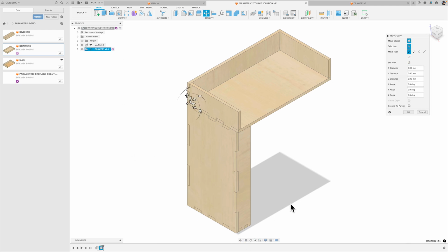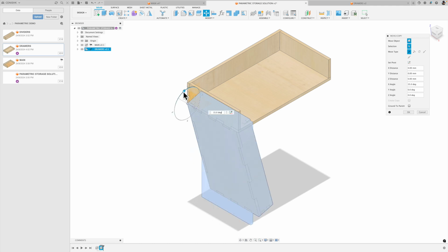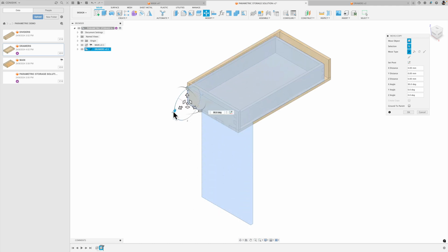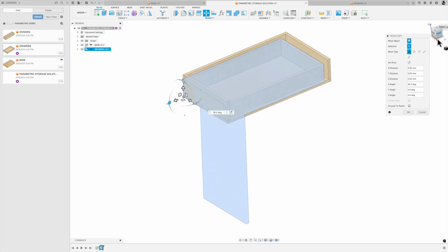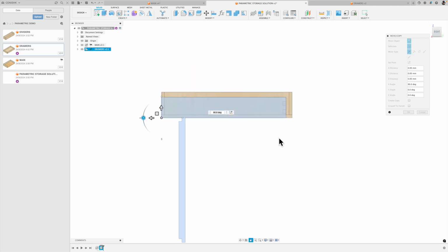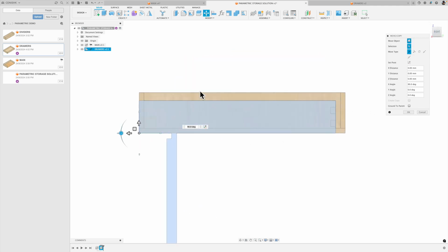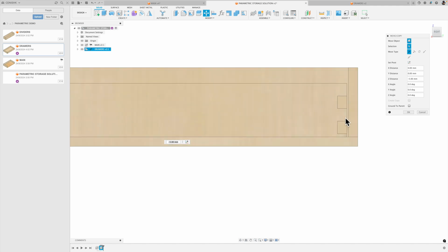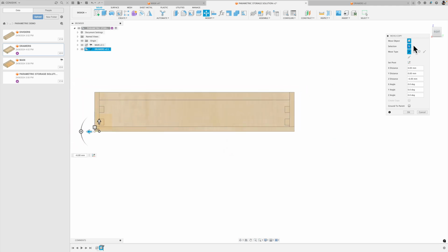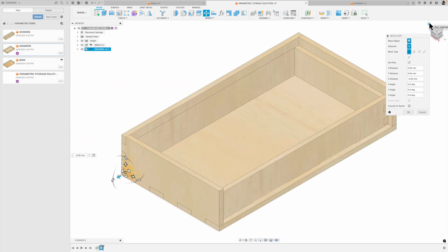And what remains now is to change the orientation. So using the manipulators for the move tool, I'll change my views to get a precise understanding of the positioning. And so we need to notice I'm using the arrows, I'm not using the square to move. The square is freely moving, and the arrows ensure that the move is constrained to a particular plane. So I use 6mm there, or added in 1 to ensure the good fit here.